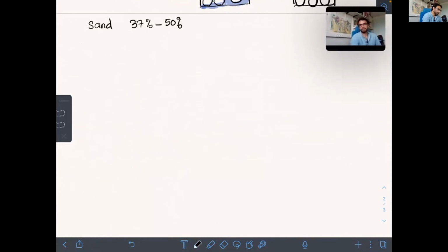So now if we take, this is just sand, like on a beach, but if we take now a sandstone, a sandstone is a sedimentary rock made initially of sediments of sand. Because it has been consolidated and compressed, the porosity is much less, and it goes typically from 8 to 38%. And then now if we take concrete, so concrete used for building, right? Obviously this is a very strong material and low porosity. We have typically from 2 to 7% of porosity.